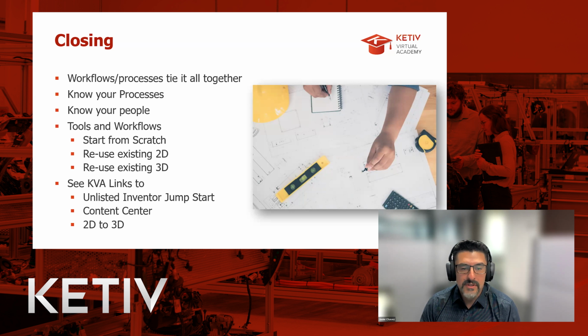Know how you're going to edit it in the future. Again, that determines what information you're going to put in the file as far as parameters. Are you going to edit the length? If so, you're going to need a length parameter. And also, get yourself familiarized with your team and get them familiarized with the process that you're developing as well.